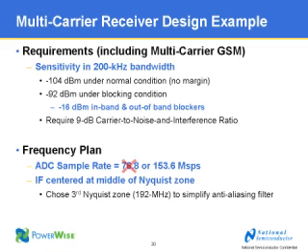So when we're talking about sensitivity, we're worried about the sensitivity in our channel bandwidth of interest. Now in GSM, the channel bandwidth is 200 kilohertz, and that's why that's on this slide here. So we're talking about the sensitivity in the 200K bandwidth. A couple of numbers that we need are shown on this slide.